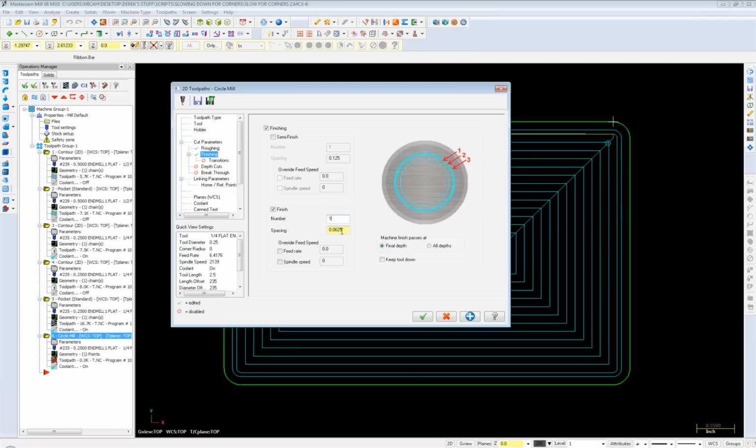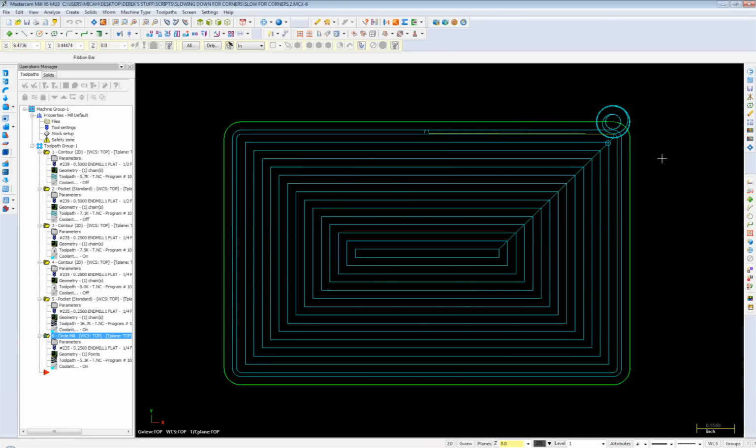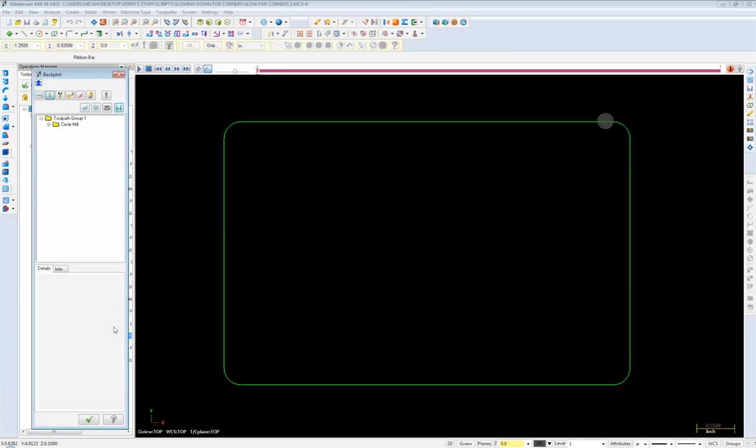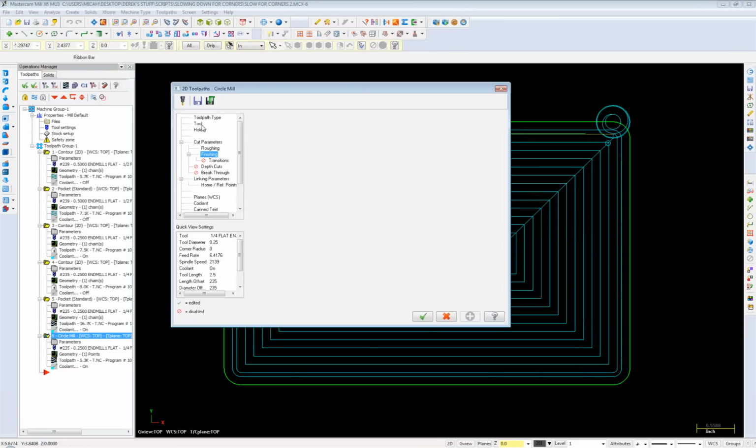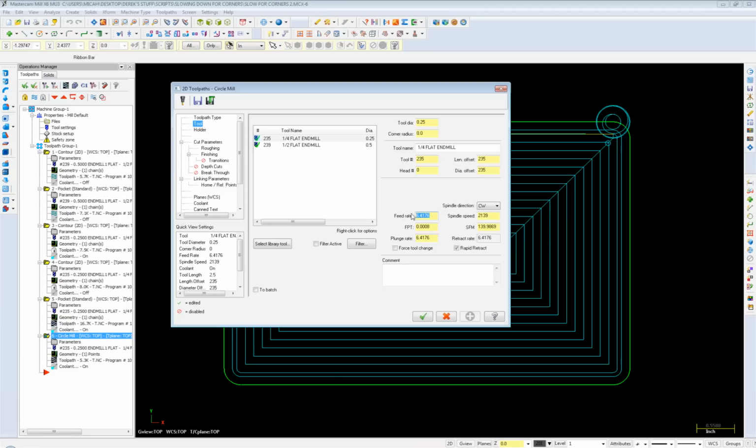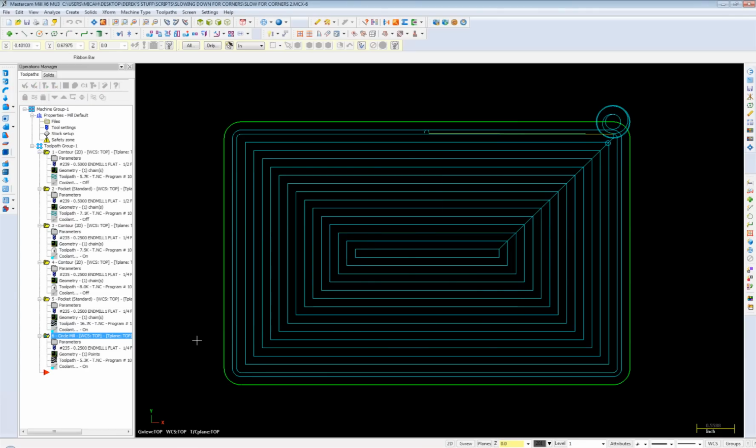I have one quick comment, Derek. As we were speaking about once before, one way to ballpark the feed rate for your machine on Circle Mill is to go into your local copy of the machine and look at your general machine parameters and your cornering acceleration, and set that to what you believe it would be on an older machine. Usually it's going to be, just as Micah said, 0.003 to 0.005. Then type in your radius and have it give you the feed rate. That way you don't have to guess. It's kind of like manual high feed.